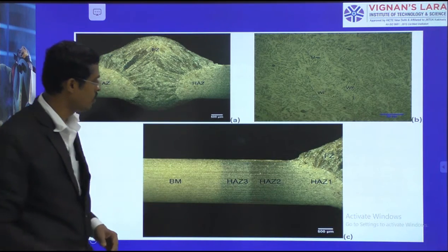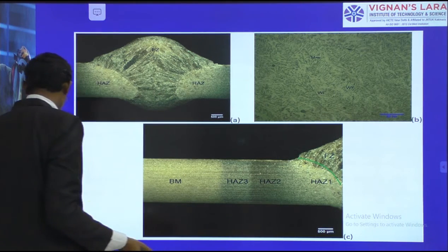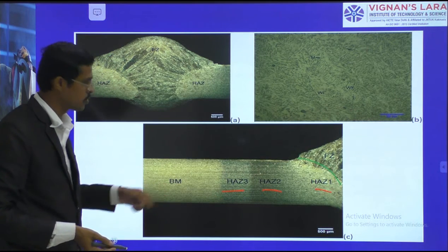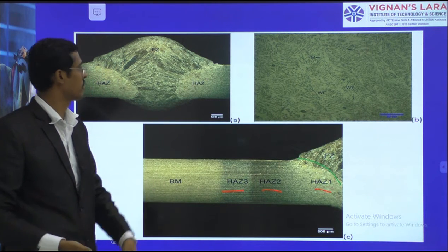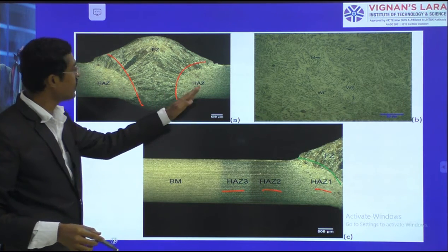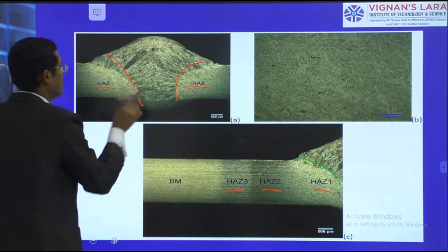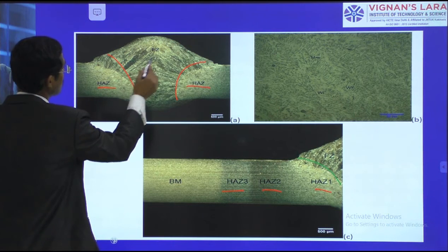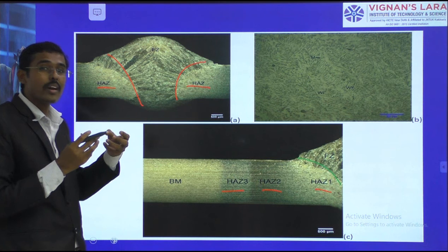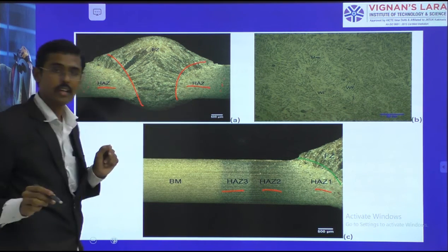So some other images I would like to show you. Here the fusion welding is there. And then heat affected zone 1, 2, 3 and at last we have the base material. So such changes will be there. See here also, it is a base metal, we have welded there. Nearer to this non-melted but heat affected zone, see this side, it is distributing there. Here in the microstructure you can see it is columnar, lengthy, because of more heat, not equiaxial grains. But nearby to that, here are equiaxial grains because it is finer,